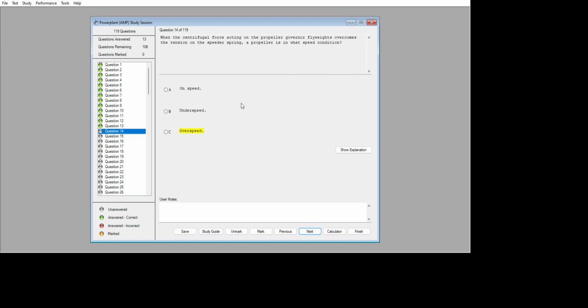What would be checked or changed to ensure the validity of a turbine engine performance check? If alternate fuel is to be used, the fuel specific gravity setting.